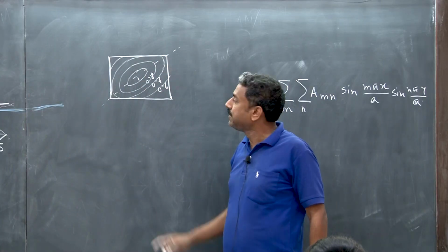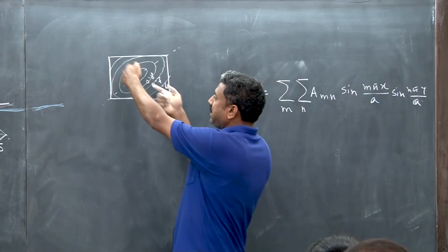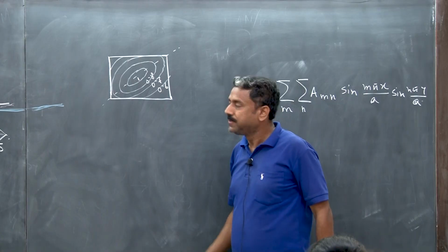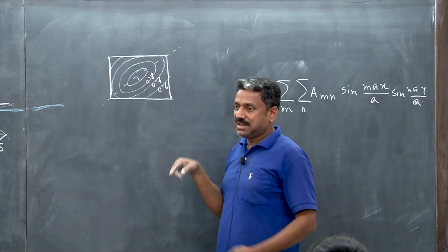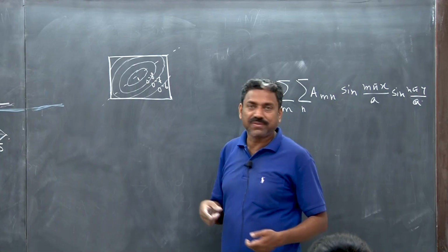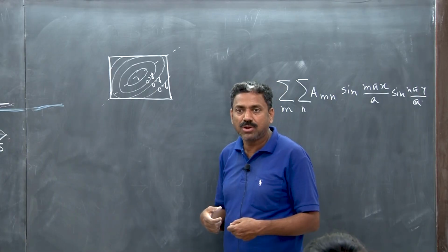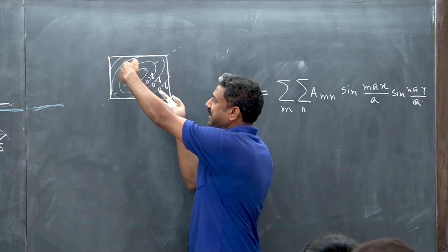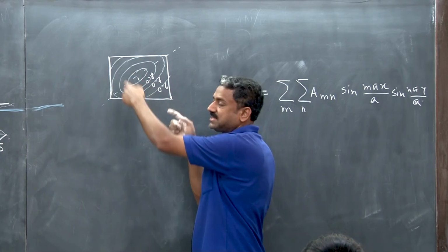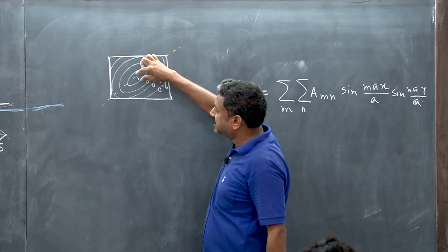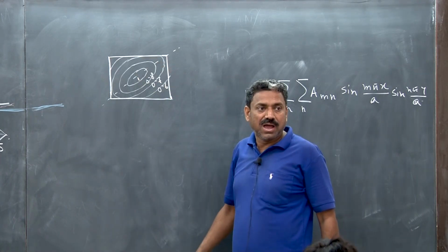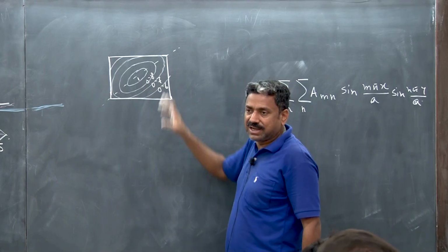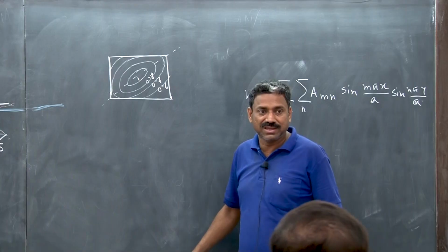You understand the surface? Now, why is it a little oblate, why is it shrunk in this direction? That is because, under shear, one diagonal will be in tension, and another diagonal will be in compression, right? So on this side it is subject to tension, so some tension stiffening is occurring. That is basically reducing the extent of this outward deflection. You understand what I am trying to say? On the other hand, in the other direction it is compression, so it is more susceptible to buckling.